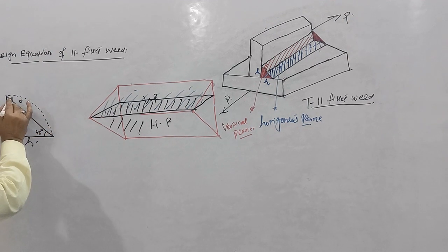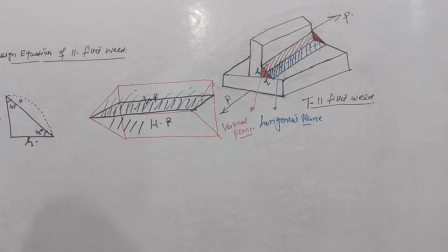This is called the reinforcement, and for reinforcement the equation we would have to derive is the parabolic equation. This is actually very difficult to calculate. So in 90% of cases, or mostly, the reinforcement is removed by machining or grinding.